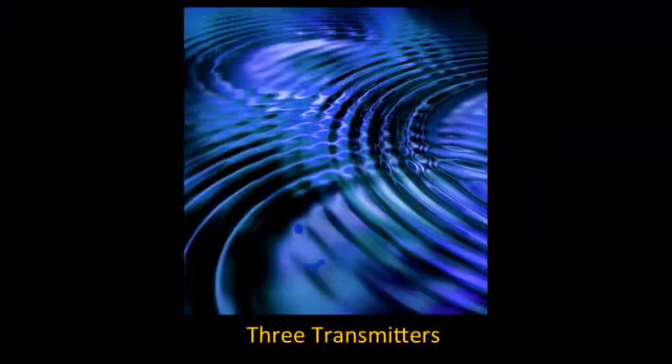Now, this is a pretty simple view of the world. We have one transmitter sending nice, clear and beautiful waves into space. But if we expand that out a little bit more, in this case, 3 transmitters, we see some waves interfering with each other. Now, it's not a big deal with the waves interfering with each other as they move through space, kind of midstream between the transmitter and the receiver. What's really challenging and problematic for us is when the waves overlap with each other right at the point that they hit the receiver, right at the antenna. That's where they're causing their constructive or destructive interference, which makes it challenging to demodulate that signal and turn it into something meaningful, the bits that you're trying to transfer.